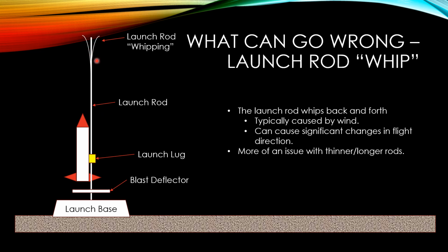However, if you start using a longer rod, and some rockets do say you should use a longer rod because the rocket may be fairly tall, like if you have a Big Bertha, which is almost 2 feet, I believe, that's going to be quite a distance up your launch pad, and you definitely want to be aware that the rod may be longer so you can have a better launch. But again, the longer rod means you've got a chance of more whipping that can take place.